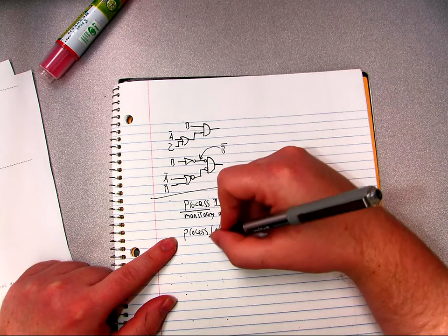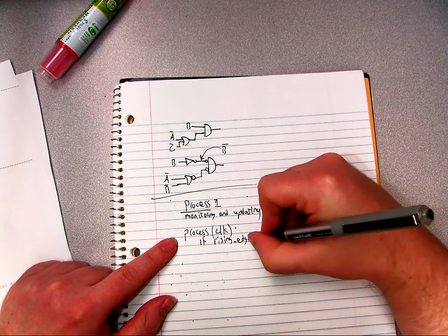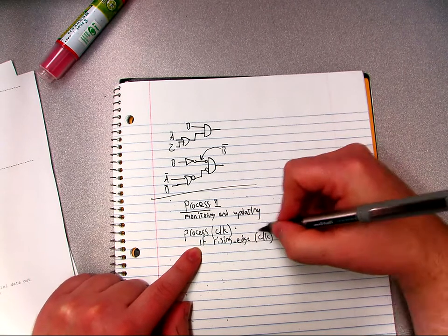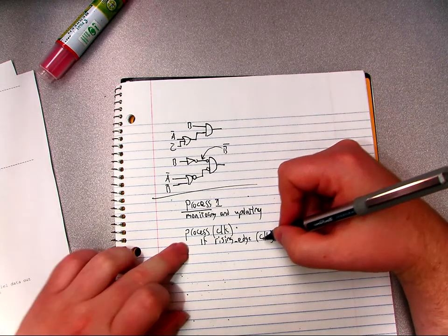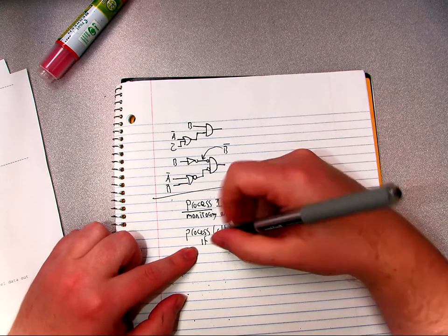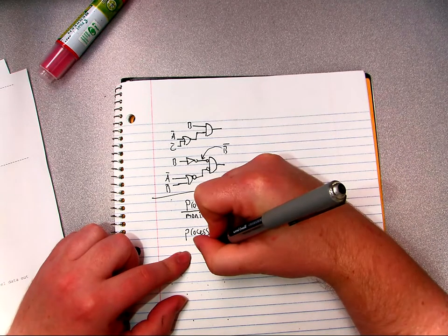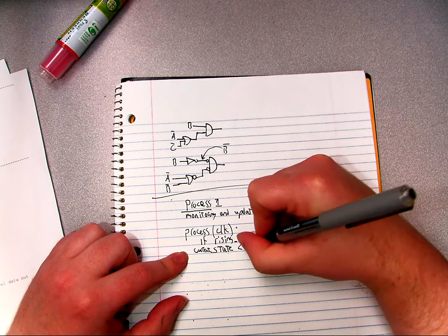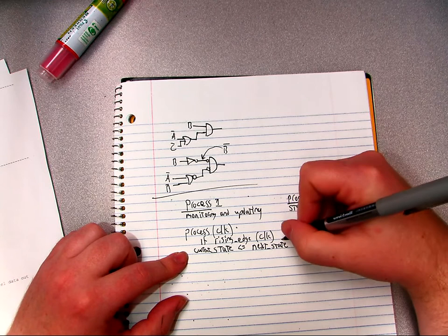Then you're going to do if rising edge of clock, then we want to do stuff, every time the clock happens. If you don't have it executing only on the rising edge of the clock, things get really confused, and we don't want that. So if the rising edge of the clock, every rising edge, we're going to say state, in fact, let's give it a better name and call it current state, is assigned to next state.